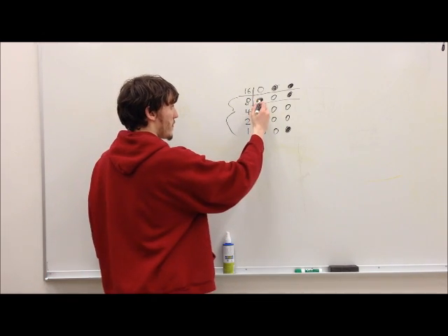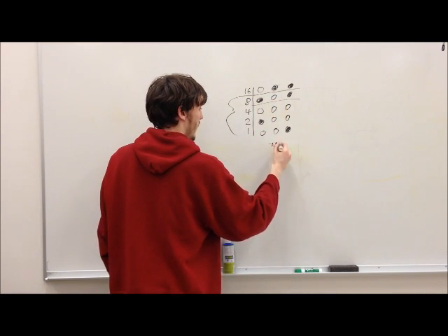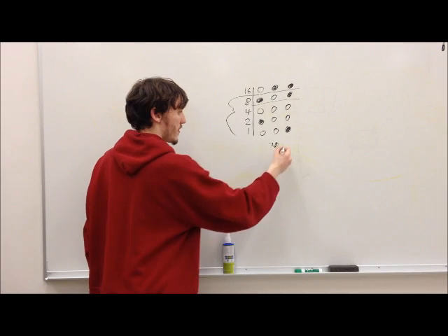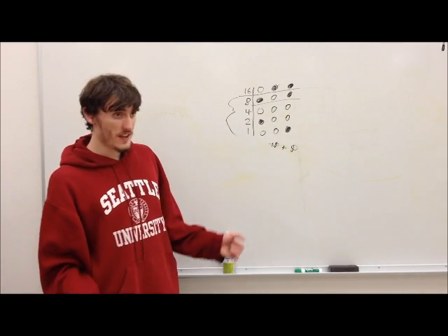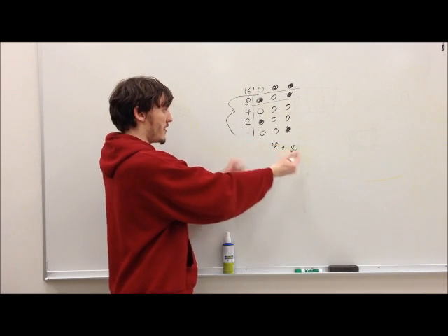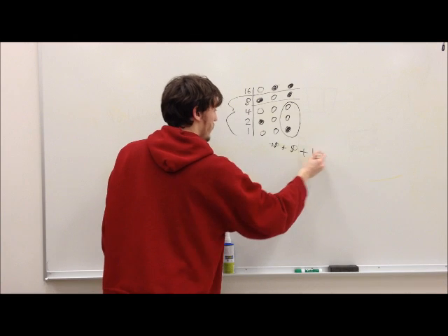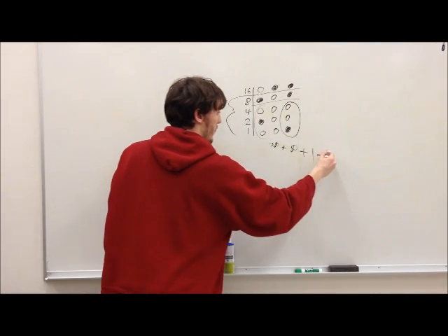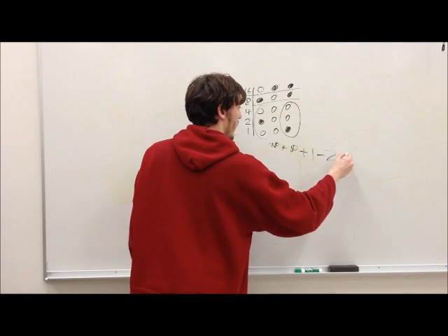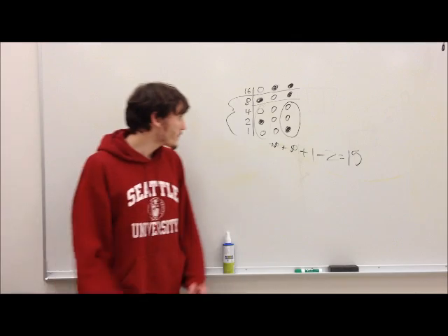So what we do is we say, okay, it's changed once here, so we add 8. It's changed once here, so we add 8. And then, at the end of our polling period, we take the lower bits at the end of our polling period, and subtract the lower bits from the beginning of our polling period, and we say that we've seen 15 pulses.